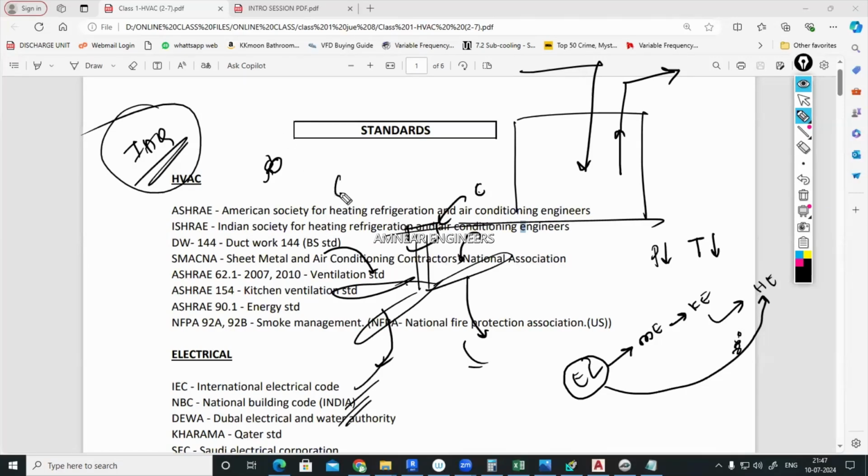Actually, if you are having a 60-watt fan inside your bedroom, this fan's watt is joules per second only, correct? So the fan is adding nearly 60 joules of heat in your space in each second. So the fan is not an effective cooling method. Fan is a sensation. It may create a sensation since it is a direct cooling technology, but effectively the fan will increase the room load.